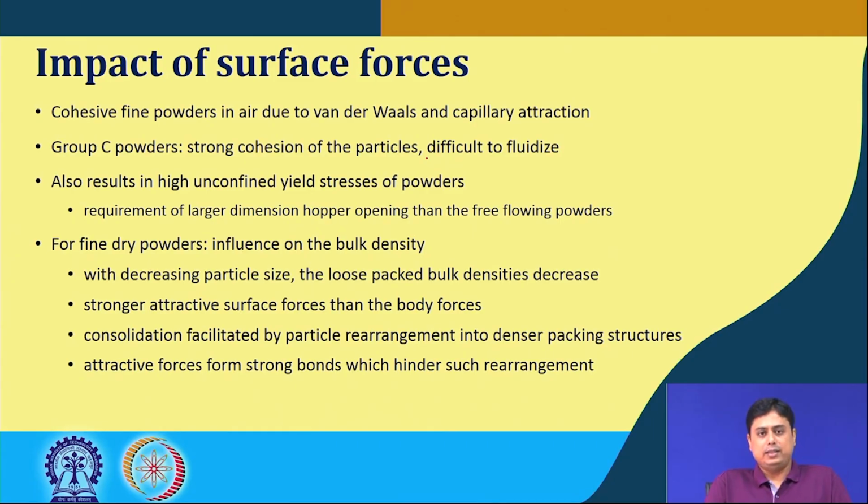But the point is that consolidation is facilitated by particle rearrangement into a denser packing structure. Because these particles are extremely small, the attractive forces are stronger than the body forces. There would be very strong attractive forces that make it difficult to rearrange.